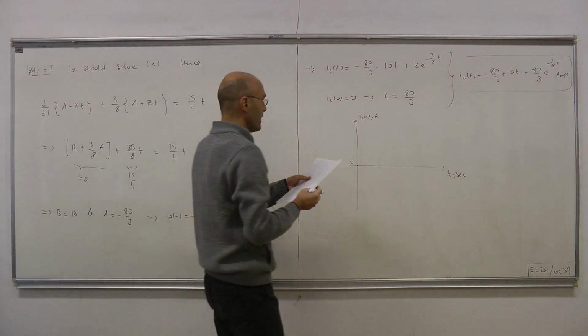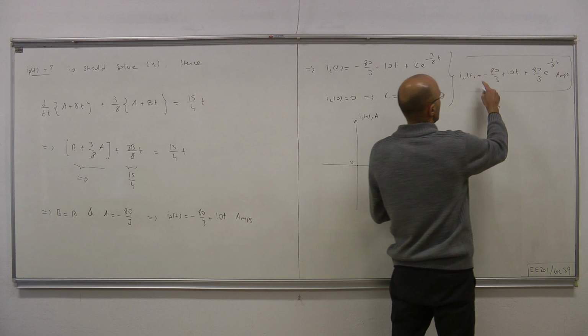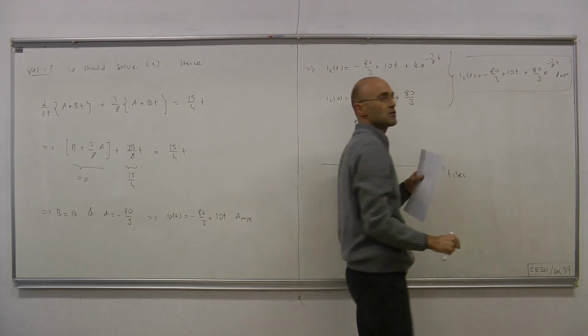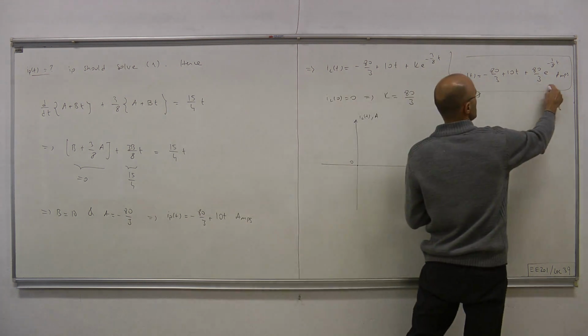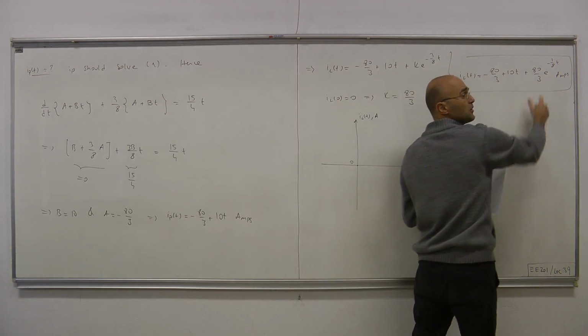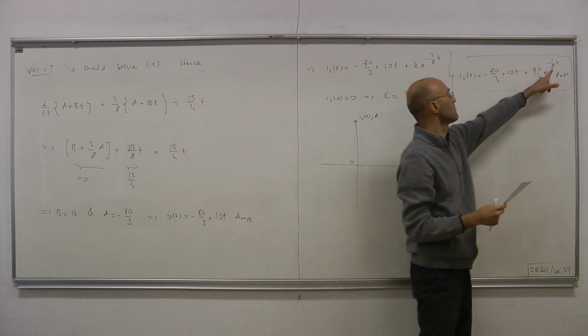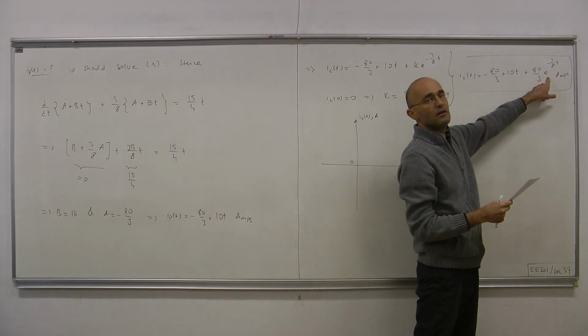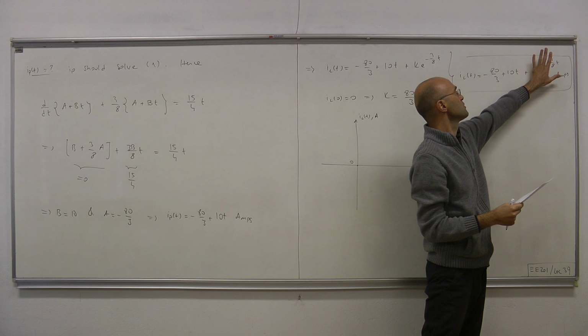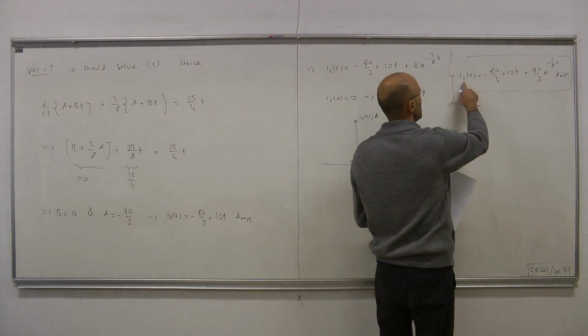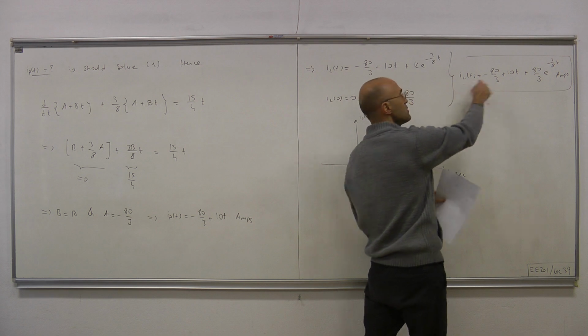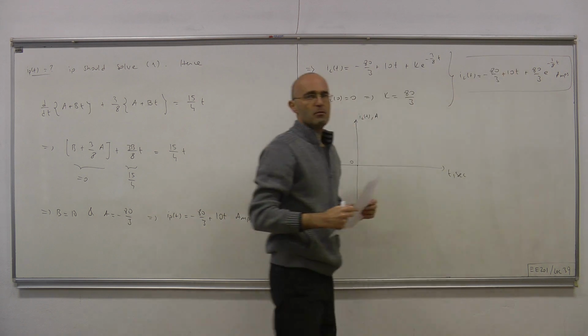Okay. So we have two pieces. Here we have the constant slope piece, or the particular solution, and then we have this homogeneous part. This can be called the transient part because as time goes on, this exponential will decay to 0, and then this will be less and less significant. And what the current is converging to is the particular solution.